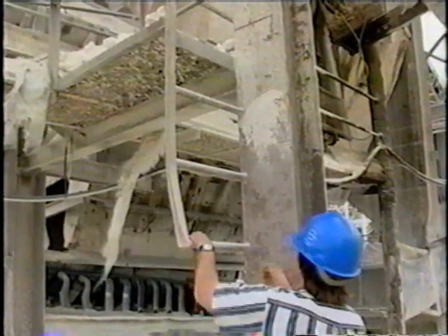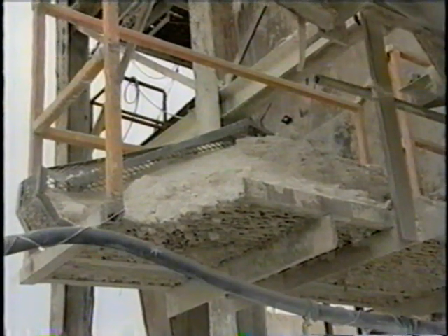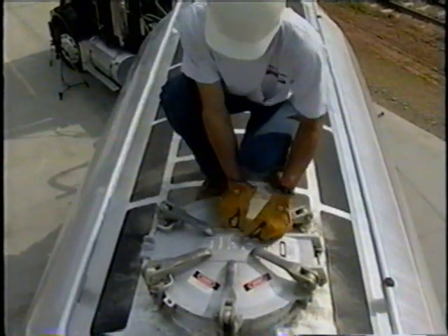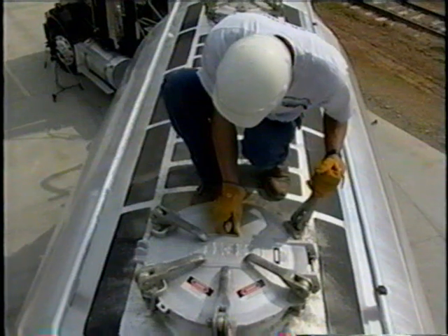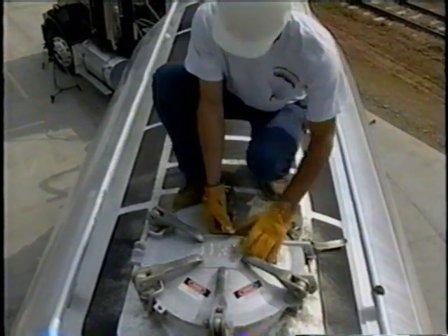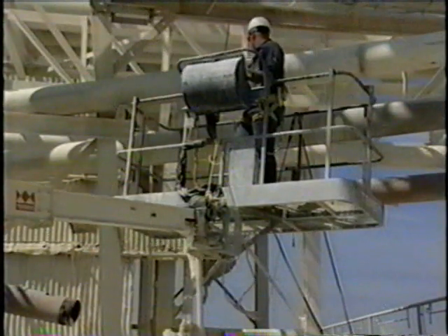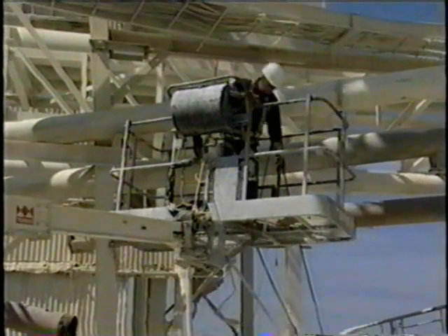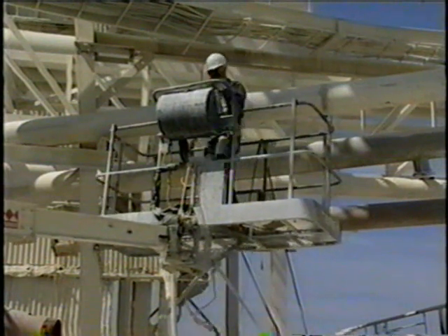Hazards in this area would be a lack of fixed ladders to reach elevated areas, no work platform at elevated areas, and not wearing fall protection devices when entering bins or hoppers, or not wearing fall protection as a tanker truck driver on top of a tanker while opening or closing hatches. Use fall protection devices in the appropriate areas, and a man lift if proper access is not otherwise available.